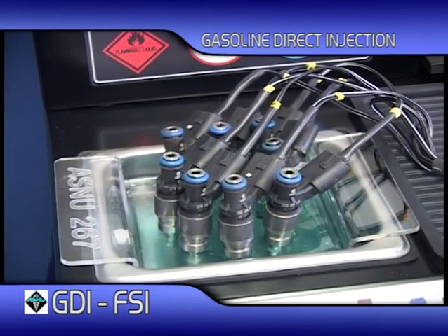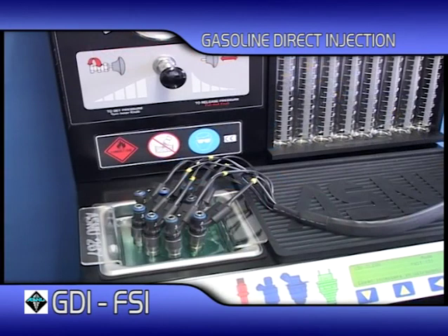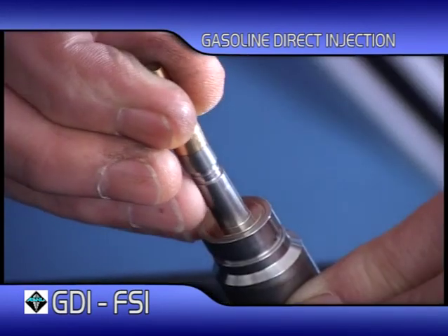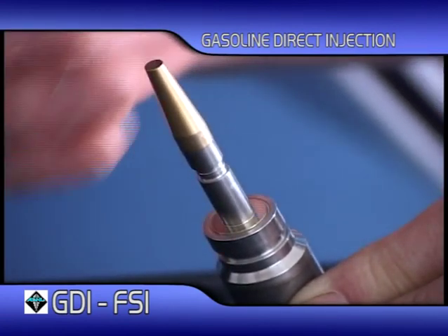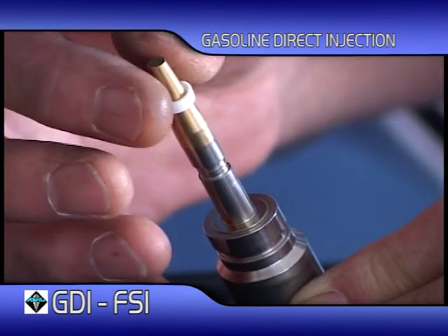Place injectors in the ultrasonic bath. Clean for 2 cycles. If the ends still have carbon on the tip after 2 cycles, replace the BioClean cleaning fluid and clean for another cycle. Once clean, you can replace the Teflon head seal using the brass cone adapter that allows fitting of the seal.